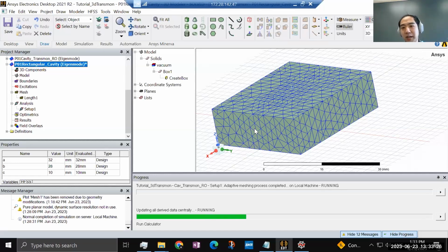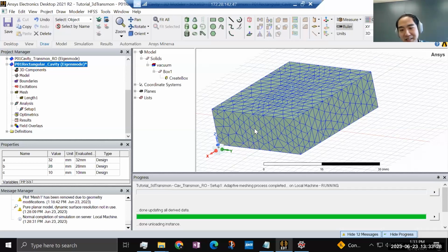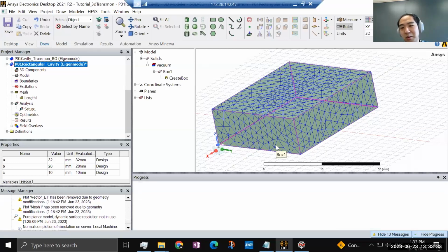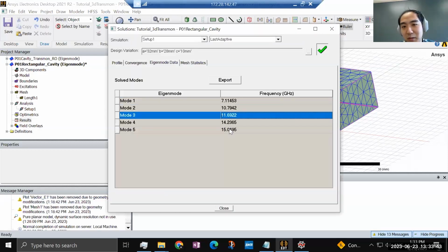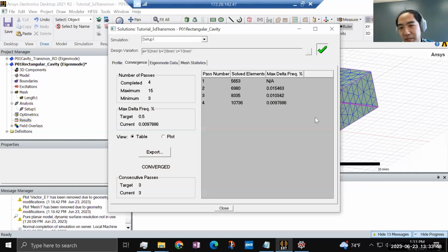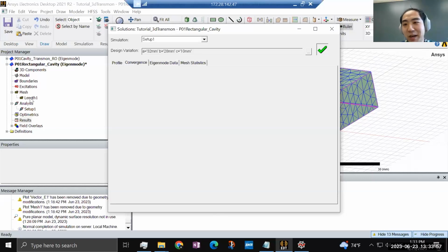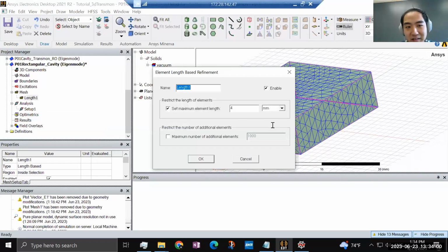But the thing we want to make sure in simulation is that it's not giving us numeric error due to the meshing itself or due to your mistake in setting up the simulation. So now what we have seen is that it basically finds the correct eigenmode frequency, if you verify that, with pretty good convergence for the numeric error itself. But if you're being careful enough, and I suggest you do it, you can change the initial condition, the initial meshing.